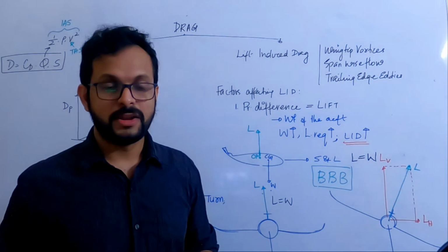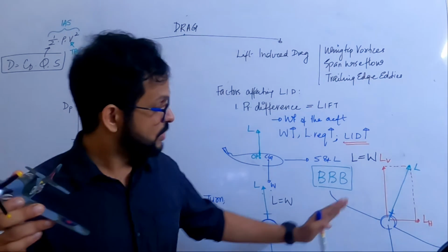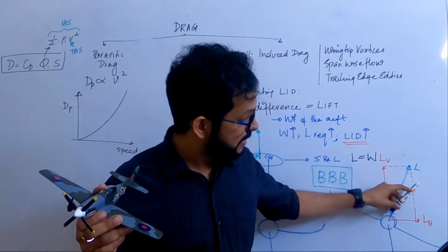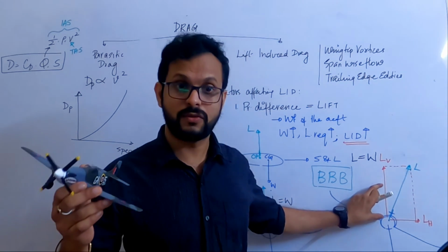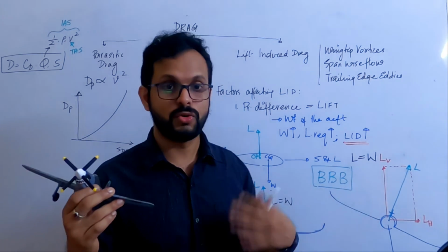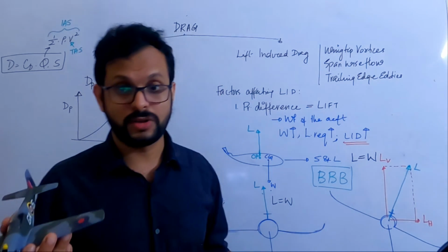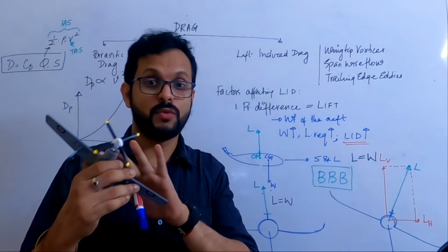Right? Now what happens when you increase the turn from 30 degrees to 60 degrees? When you make the aircraft bank more, the lift is going to incline more, and therefore the vertical component is going to reduce further. Now you have to pitch up more if you don't want to descend. Now don't get confused. As I told you, we'll draw separate diagrams for this under turning. Basically what I'm trying to tell you is the more you bank, the more you have to apply back pressure if you want a level turn.